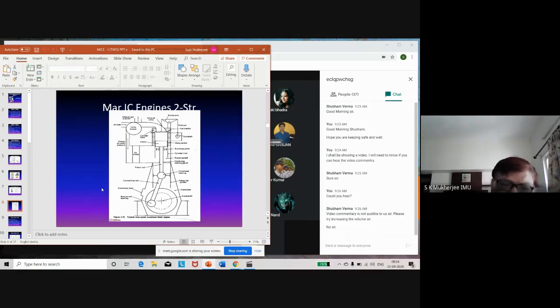So motion of the fluid in the shaft's arrangement is what provides the satisfactory oil film between the shaft and the bearing. That is why in any bearing you have a clearance. That clearance enables the shaft to rise and allow the oil to go underside of the shaft.